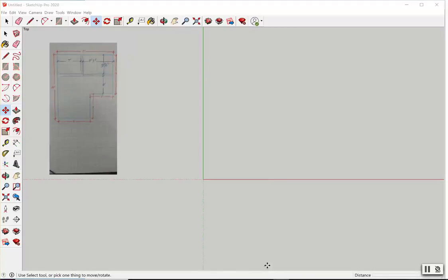In Google SketchUp, there are multiple ways, as with everything, that you can draw a space. If you are trying to create just an exterior view of a building, or basically a simple plan, you would just measure the perimeter and begin to outline it in Google SketchUp, and then you will go from there. What that is called is creating an as-built. An as-built is a drawing of an existing building, and those details are already provided for you because you're going inside of a space and taking the existing measurements.